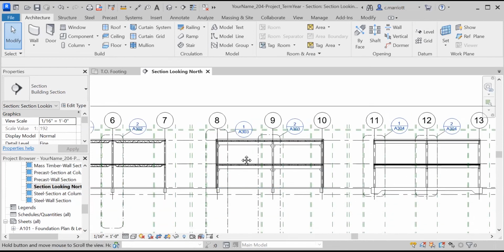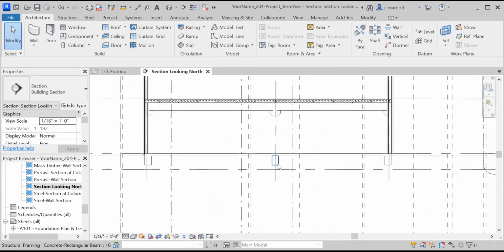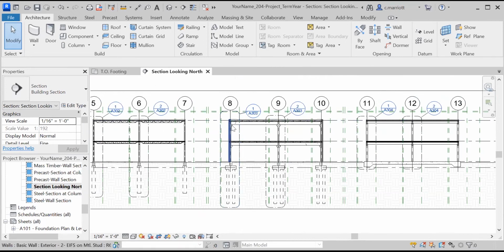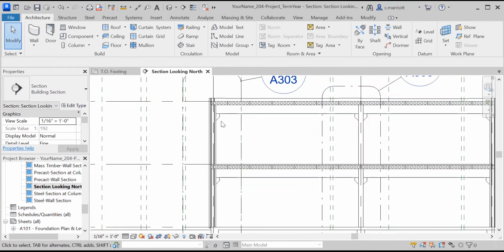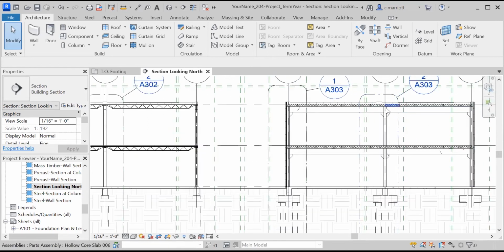And you can see that the piles and the grade beam also shifted. I'm going to do the same thing over here. Now, I'm going to need this one though. If I want these to be symmetrical, 23 feet, 6 inches, I'm going to need to move this one over 3 feet. I move this one over roughly 18 inches. I'll move this one over the actual dimension, which is basically close to 36 inches.